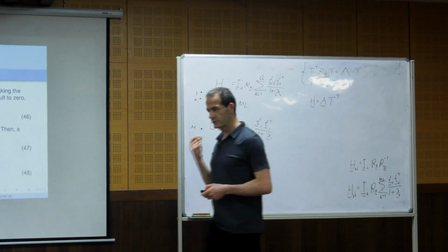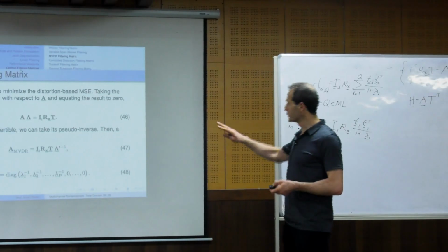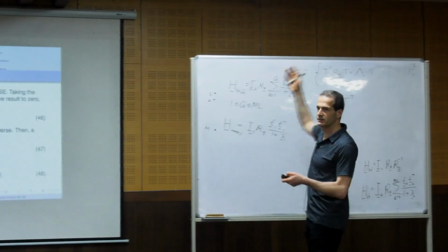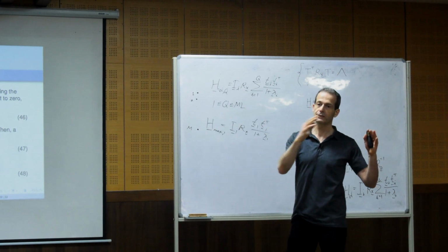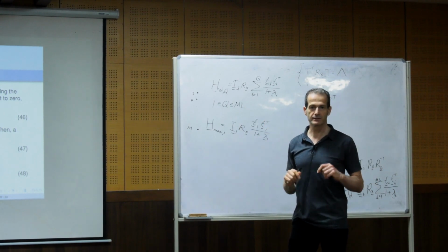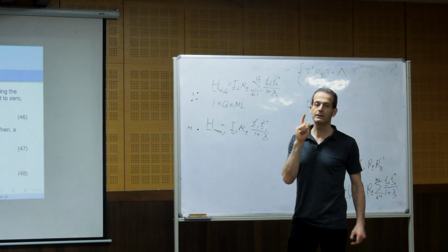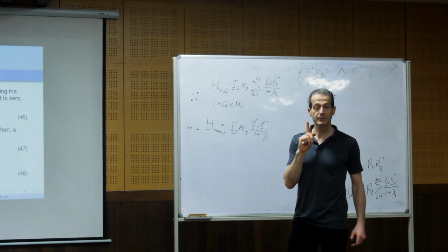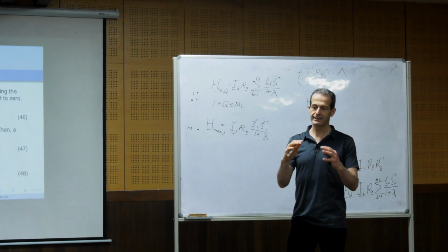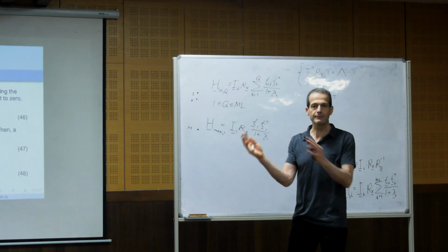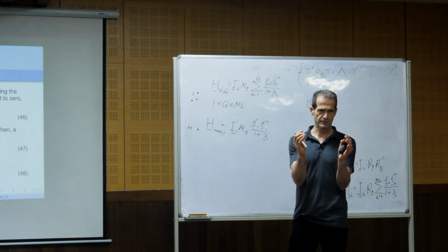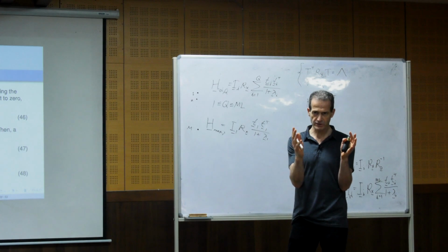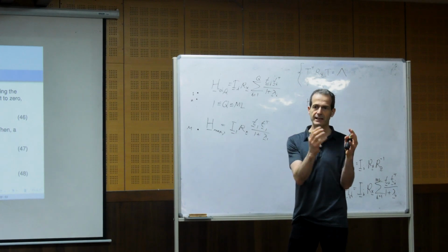So how do we do it mathematically? Once we do it in the transform domain, it's much easier because we can separate. We can have an optimal separation between the signal subspace and the noise subspace. What does optimal separation mean? It means that the dimension of the noise-only subspace is the largest, because we have the least number of eigenvectors or basis functions that span the signal subspace.